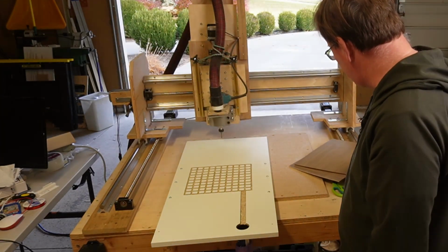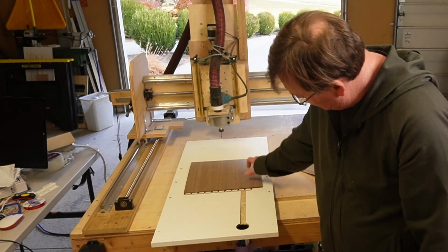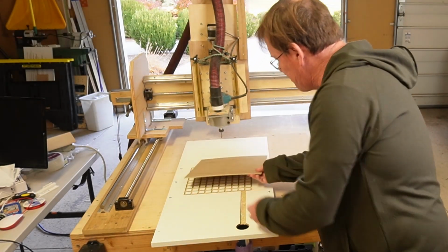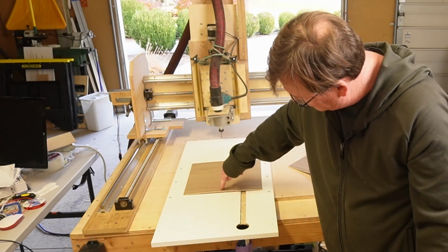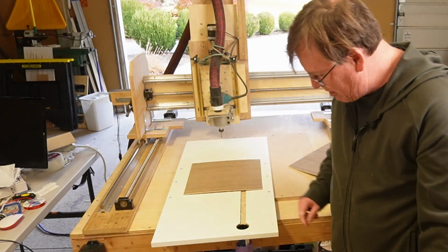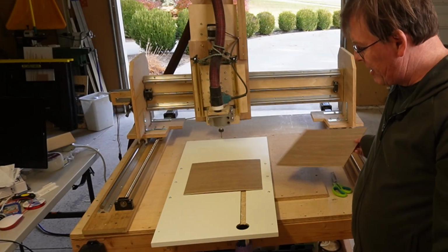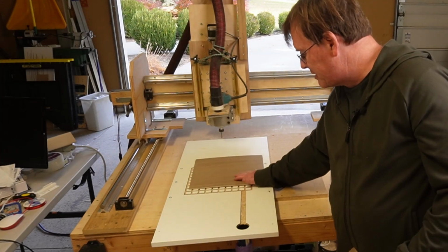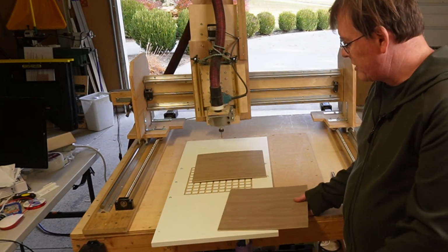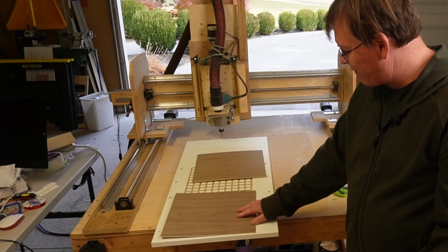And I'm going to have a board that's bowed so you can see it pull the bow out. Okay, and let me turn it so that the bow is maximized. There's over 1/8 of an inch rise in the center of this board right here, which would be a disaster to V-carve. And then we need to seal off this channel. You could do it with strapping tape, but honestly, the easiest way to do something like this is just put another flat board on there. Don't put it over your screw or you're not going to get a flat seal.